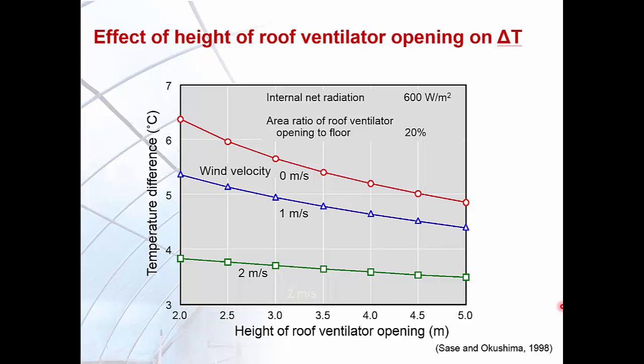This example shows that a taller ventilation opening results in greater greenhouse capacity to help prevent sudden changes in greenhouse internal climate, and that improves the spatial uniformity in the greenhouse as well. An additional advantage of a taller greenhouse is that it promotes ventilation caused by the chimney effect and the mixing of cooler incoming air through roof ventilators with internal air, because the location of the roof ventilator opening is raised.